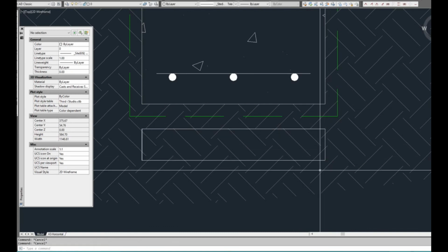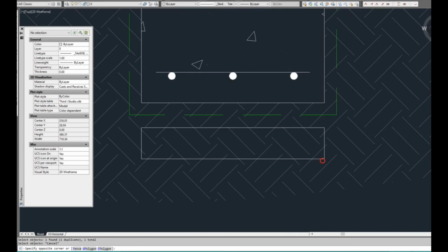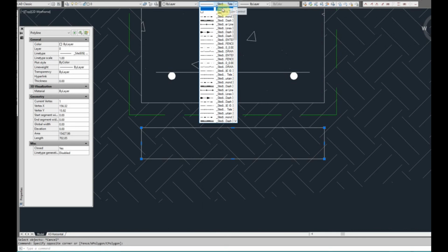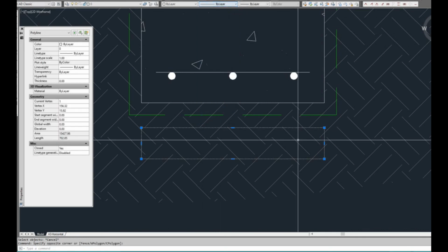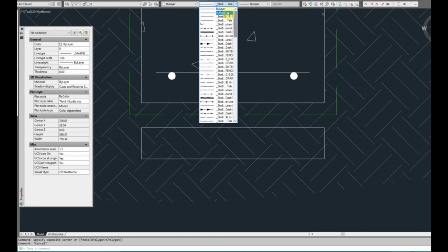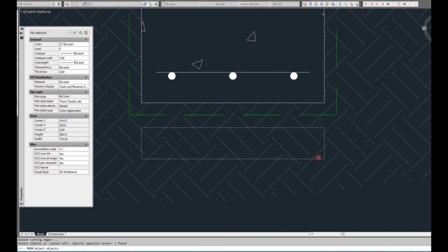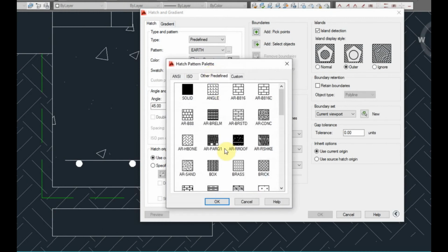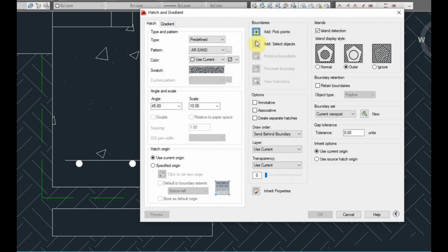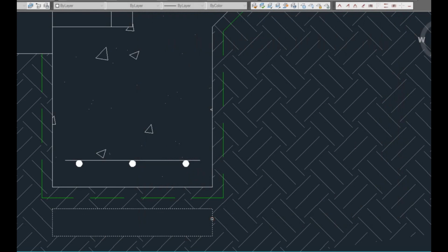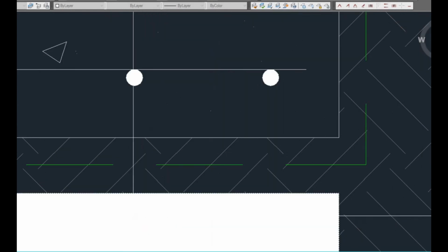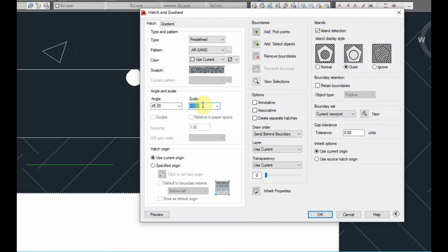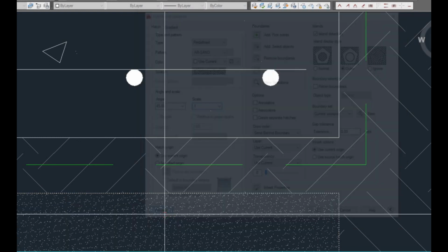Generally you'd have the right dimension for the sand, packing sand. I still can't seem to select that for some reason. Maybe it's to do with the line type that's selected. I think that might be the problem. So TR, there we go. Now I've trimmed out the hatch, and I'm going to type B hatch again. I'm going to select the slab, select sand, select objects, press space, press preview. That's very dense. Press space again, and we'll try 0.1 preview,